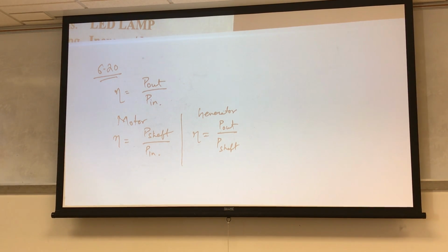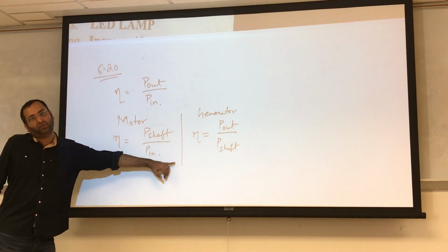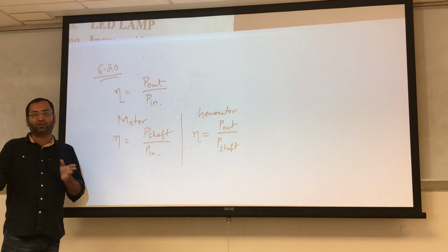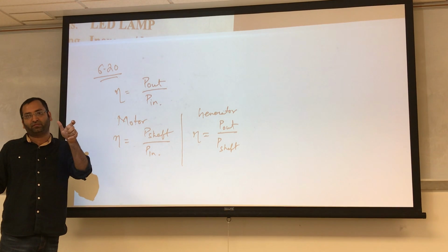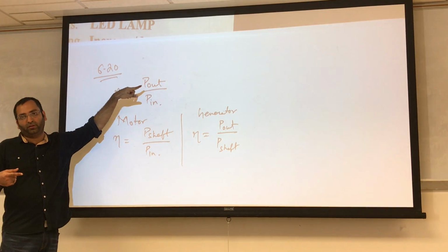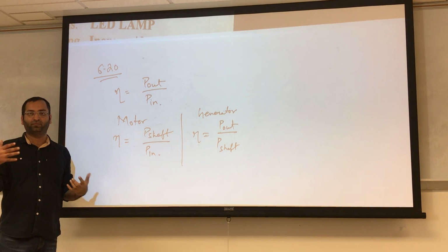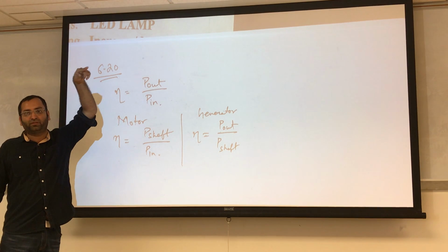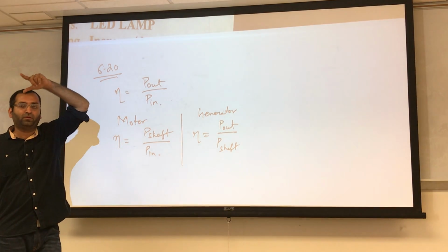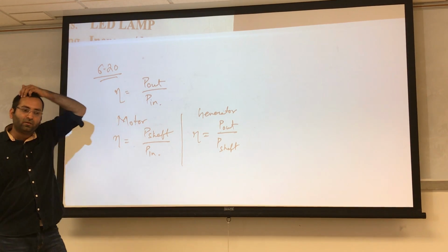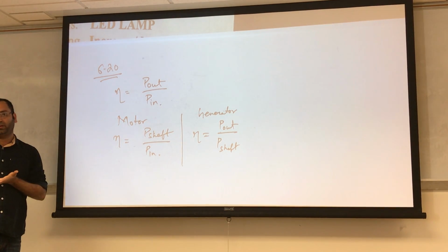Also, induction machine is termed as a frequency converter because you can see the rotor frequency changes, right? When we were discussing the example in PSCAD, we have a 60 Hz input, but depending on slip we have a different frequency, like 12 Hz, 6 Hz or something like that. But we also have power electronic converters.